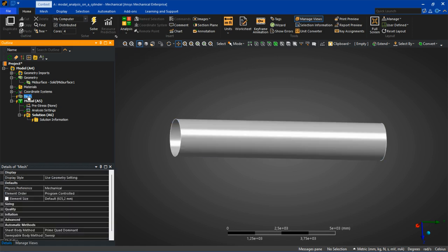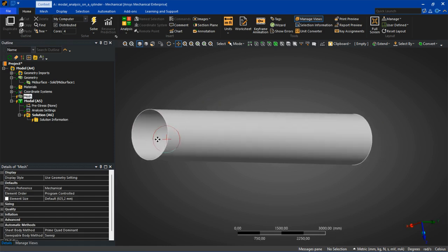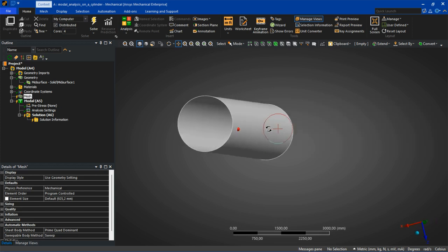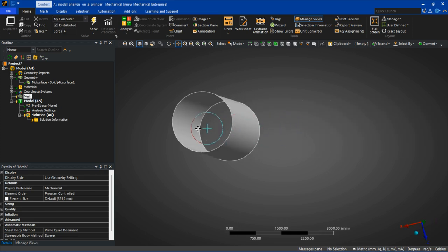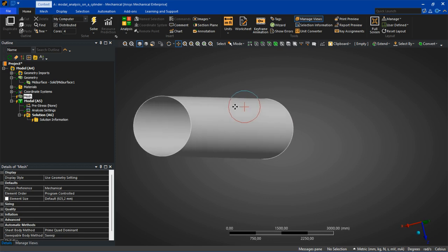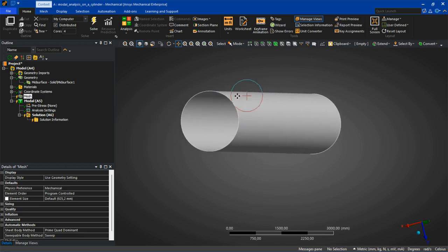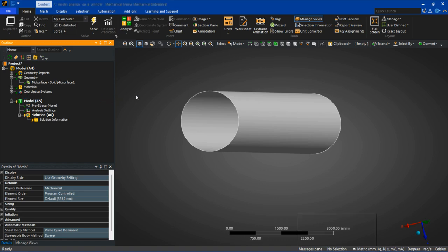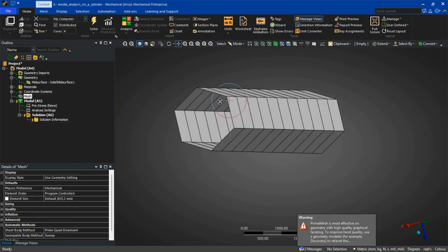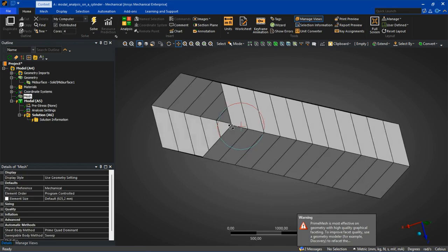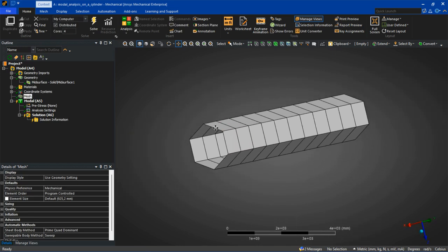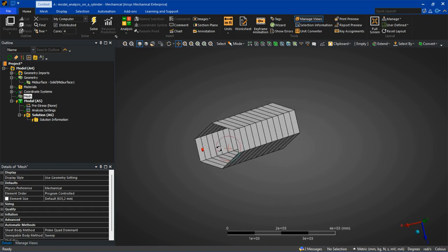For the mesh, you can generate it automatically because this is one of the benefits of having a shell element. Why? Because with this geometry the mesh is really easy. That's why I didn't want to work with solid, because solid can be easy as well since this is symmetric, but with the shell element it's fine. It's going to be a great mesh. Let's see, generate mesh. Okay, you can see how you have it. This is not a really good mesh. You can see it's deformed.